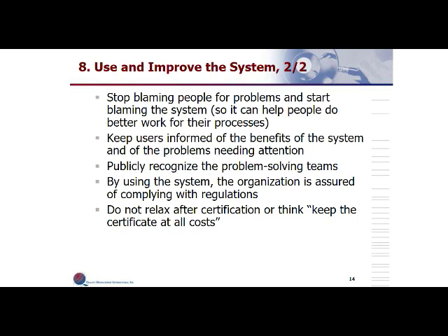Therefore, if you're doing root cause analysis, some is simple, the department can do it. Others are complex or difficult or have other departmental involvements. So you may have to have a problem-solving team. You have to train them. We have the Ford Motor Company's 8D method, the basic 5 Why method, or you may find, for example, it's complex or the design is already ready. You may do FMEA, failure mode and effects analysis. You could look at mistake proofing your system. So there are various tools and methods you could do root cause analysis with using a team.